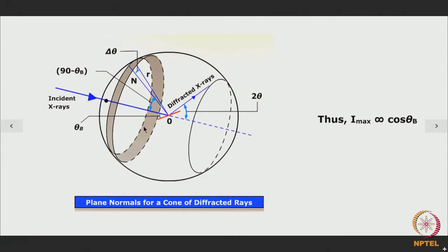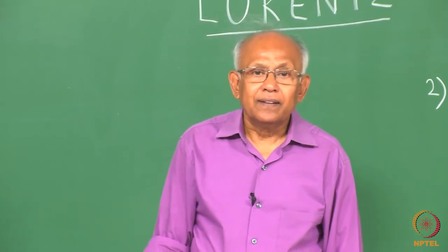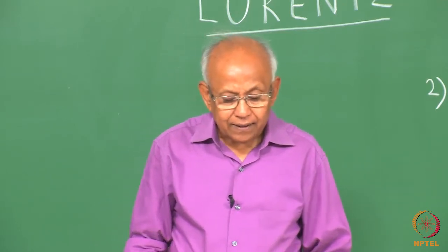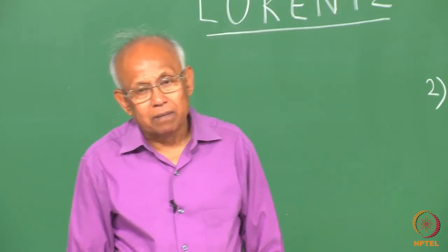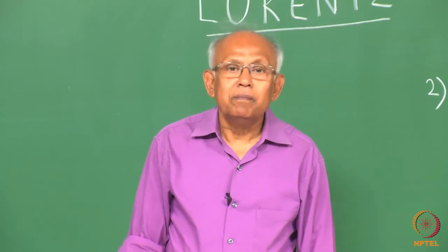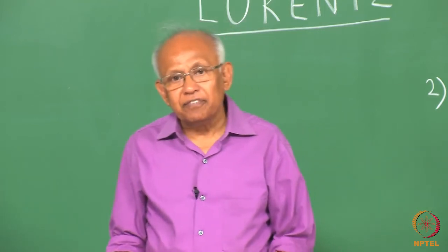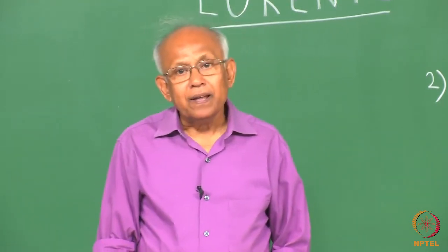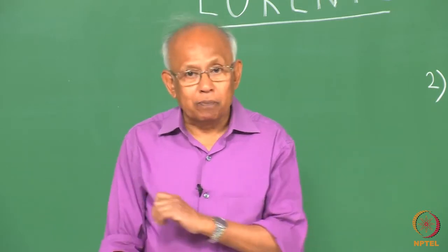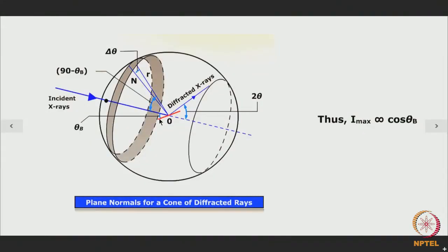element. And if we consider the total number of crystallites in the sample at O, then the total number of crystallites will be proportional to the area of the entire sphere. So, you see that the area of this ribbon-like element will vary depending on the HKL plane. That is the reason why, even though we have the crystallites arranged in a very random fashion in the polycrystalline sample, the number of crystallites which will give rise to diffraction from a particular plane will vary from plane to plane. So, in this particular case, diffraction will occur from a number of crystallites whose number is proportional to the area given by this ribbon element.